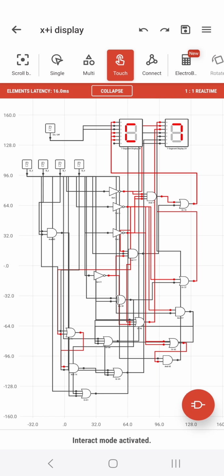0000 for a student with their roll number being 7 as the last digit, the 7-segment display must display not 0 but 7. So if the input is 0000, normally what it will display is 0. But in this question that I have given, they need to design a circuit which will display 7 since their roll number's last digit is 7.